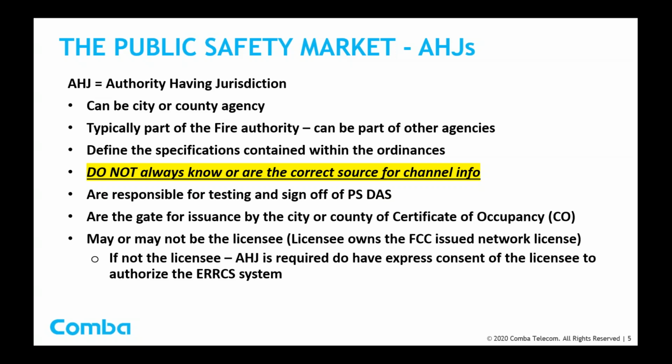But be aware, many times the AHJ don't always know, nor are they the correct source for technical information like channel information, how much power to be delivered to the tower, etc. So if you don't have that, you're going to have to dig. Typically, they are responsible for testing and sign-off for the public safety DAS. And again, Dave Adams from P2Tel will go into that in more detail on next week's installment. Typically, they are the gate for issuance by the city or the county of the certificate of occupancy.